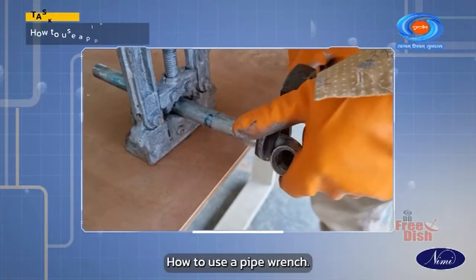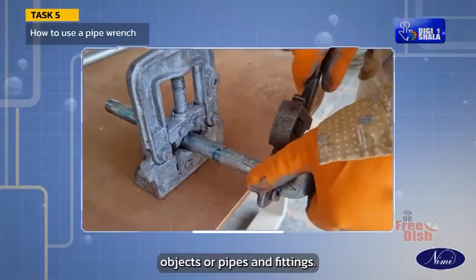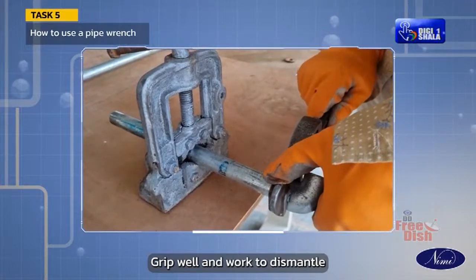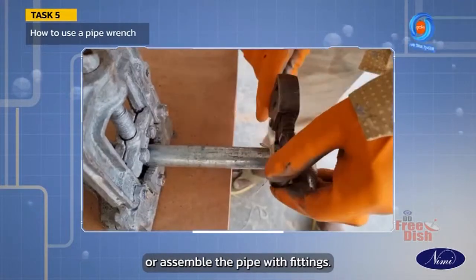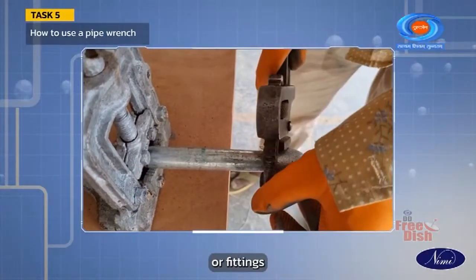How to use a pipe wrench. Place the pipe wrench on round objects or pipes and fittings. Grip well and work to dismantle or assemble the pipe with fittings. Use the correct size pipe wrench according to the size of the pipe or fittings.